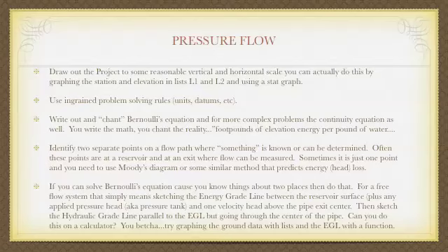If it's a free open flow problem, it's pretty easy to solve graphically if you know the velocity energy, if you know the velocity head, and you literally just draw a line between the free water surface and one velocity head above the pipe center. That is your energy grade line, and then you draw the hydraulic grade line parallel to that running through the pipe center. Those are really straightforward problems, and what you see is that is the next step up from calculating the velocity of the flow as the square root of 2gh.